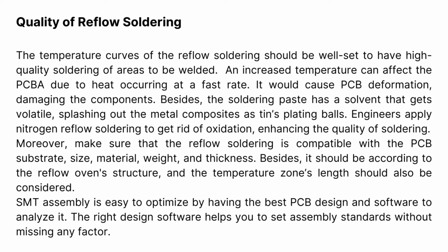Quality of reflow soldering. The temperature curves of the reflow soldering should be well set to have high quality soldering of areas to be welded. An increased temperature can affect the PCBA due to heat occurring at a fast rate. It would cause PCB deformation, damaging the components. Besides, the soldering paste has a solvent that gets volatile, splashing out the metal composites as tin plating balls. Engineers apply nitrogen reflow soldering to get rid of oxidation, enhancing the quality of soldering.